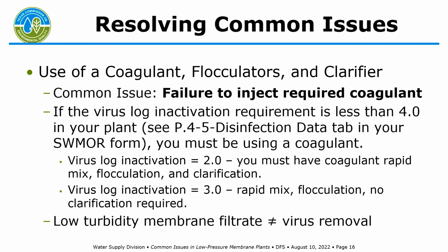Here's another one. It's not exactly directly related to membranes, but it's the use of a required coagulant. Operators sometimes think that, as I mentioned before, getting equally low turbidities with or without the use of coagulant means it's okay to stop using a coagulant. Well, the pores of the membranes and low pressure membranes are much larger than virus particles, and uncoagulated virus particles will pass directly through the